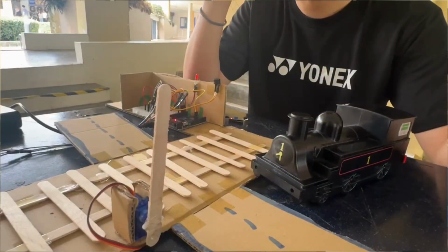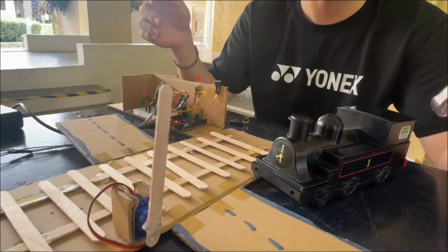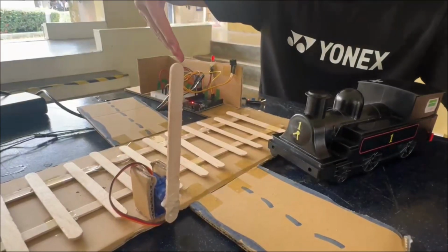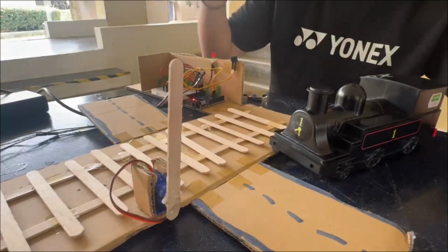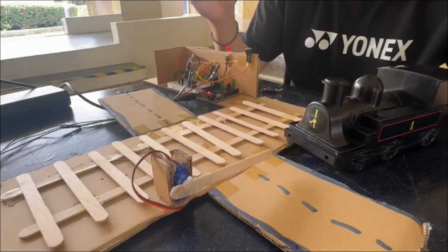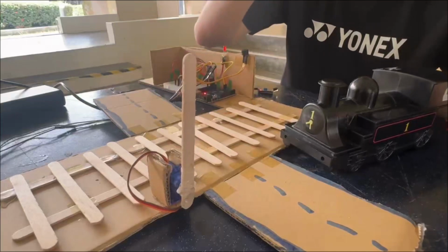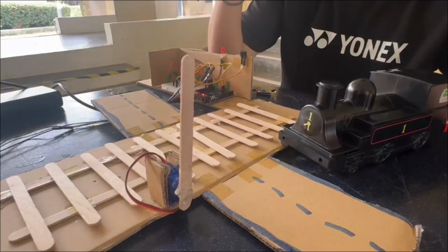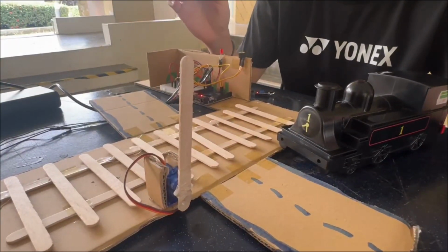Now I'm going to talk about the objectives of our project. First, to design and implement an automatic railway crossing gate system using an Arduino Uno. Second, to utilize the IR sensors for real-time train detection for both the approaching and exit sides of the crossing. Third, to control the servo motor as the gate mechanism that opens and closes based on the sensor input. And the last, to write the C program that integrates sensor reading with the motor control logic.